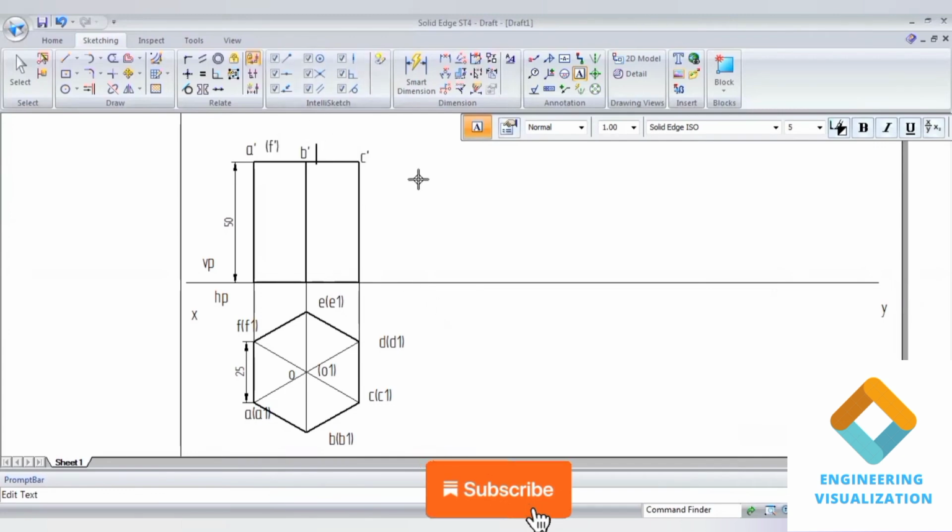From the front view, A dash, B dash and C dash are visible, and D dash, E dash and F dash are not visible. Not visible means we should write them within brackets. In the same way we write the same thing for the bottom face also.